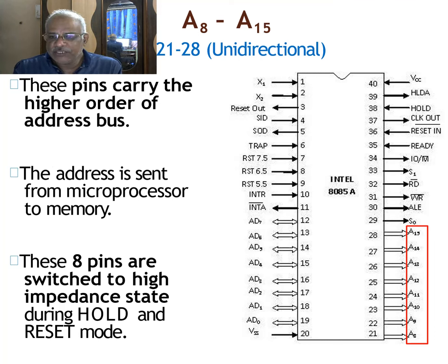Now we will shift our attention to the next group of pins, that is from 21 to 28, which is termed as A8 to A15. The direction which is important to note here is outward, and the arrows are shown as hollow arrows because they are part and parcel of a bus. Means they form a group, and that group transfers either data or the address to a particular IC. Means it is a hardware connection, and all these pins are acting in a group.